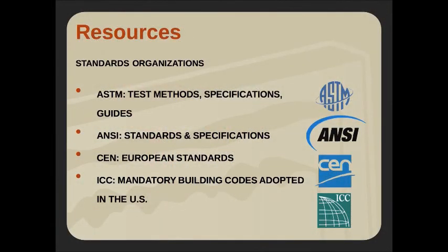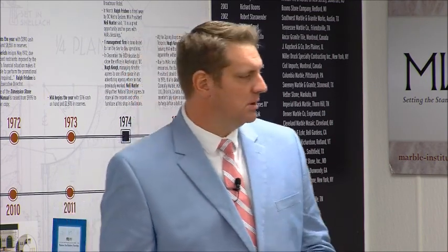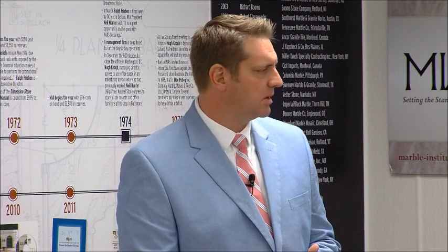We use the ASTM test methods and specifications guides often and regularly in the stone industry. That's where all of our testing information comes from, be it our flexural C880, our C97 density tests, our compressive tests, what have you. They've set the parameters and the guidelines on how those tests are to be performed on each and every material, and so we adhere to that and get our data from that, and we can make well-informed decisions from there.